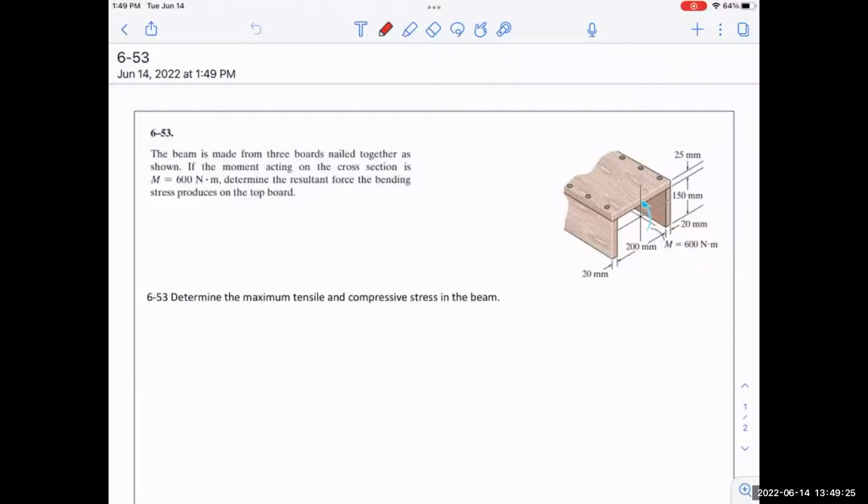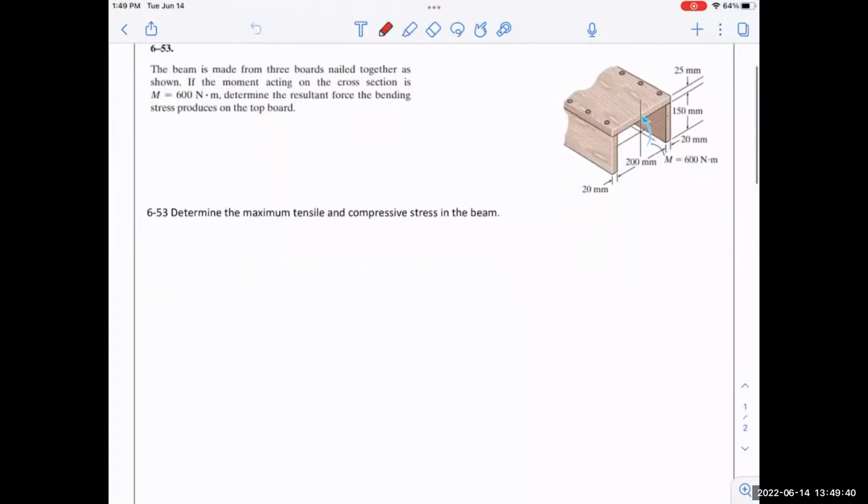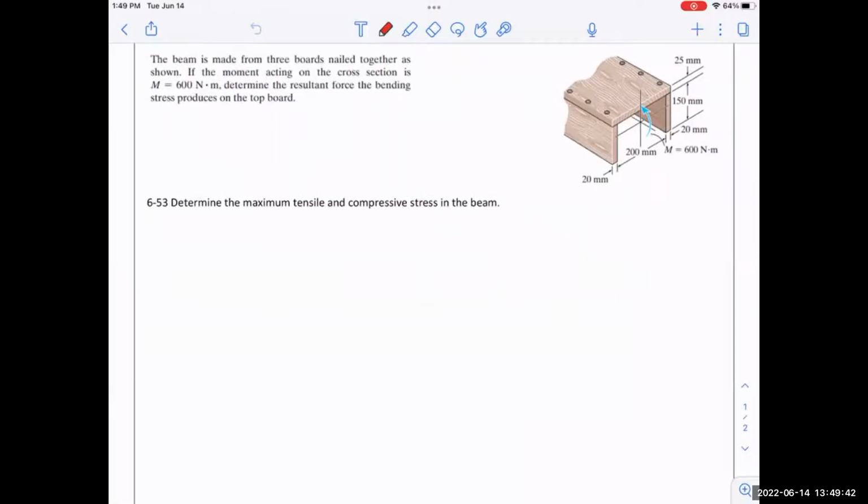So the problem you run into very quickly is the D. Did you notice that? Because how far is it from the neutral axis? Well, if you don't know where the neutral axis is, then you can't know D. So you can get that, you can get the 1/12. So let's start on that maybe down here. So let's see, I'm trying to get I.